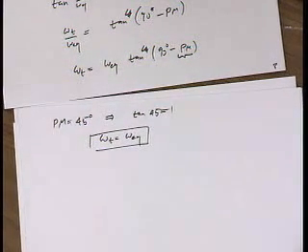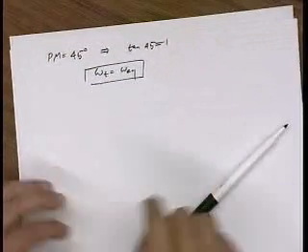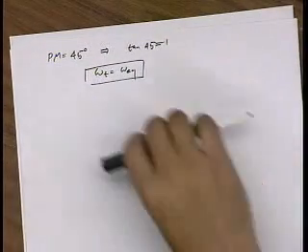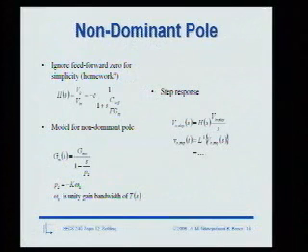They in fact use higher, 60 degrees, maybe even 70 degrees. So what's the optimal phase margin, or what's the optimum location for your non-dominant pole? And to answer that question, we can look at the classical way of doing it. The classical way of answering that question is what? Take a control class. You analyze it in terms of damping, right? You say this is an equivalent second order system, and you define a Q factor. There's critically damped, there's underdamped, there's overdamped, and you can do it that way.